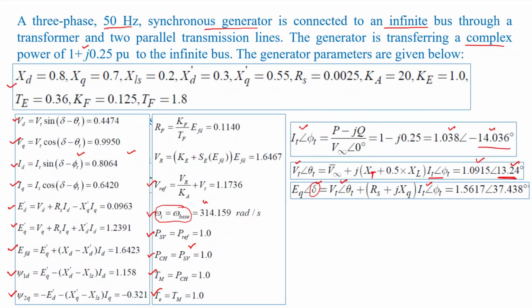In the case of small signal stability analysis, it is essential to linearize the system because it concerns small disturbances, and if we can linearize the system, we can very easily assess the small signal stability. In order to linearize the system, we need these initial conditions essentially. We'll also talk about how to linearize a system, in this class or the next class.